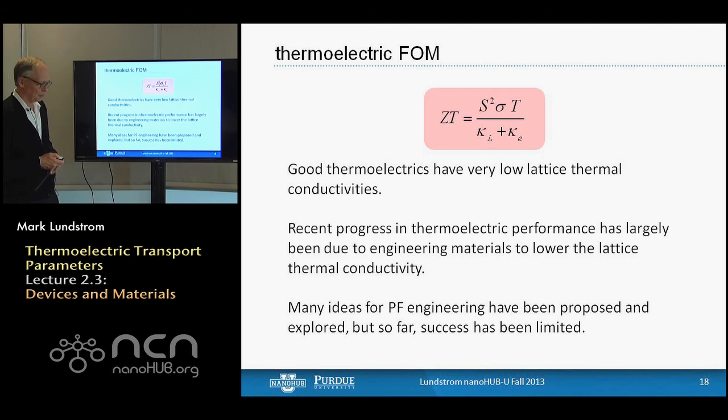Okay, so about ready to wrap up. We've been focusing on trying to understand this thermoelectric figure of merit, how to optimize it for a given material, how to select the material that will have the biggest possible thermoelectric figure of merit. Good thermoelectrics tend to have very low lattice thermal conductivities. The recent, very significant progress that's occurred over the last decade or so has all been about engineering the lattice thermal conductivity, and we'll talk a little bit about that in Lecture 5.